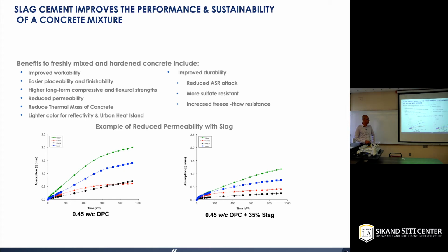It can also react with the alkali in your cement and reduce the ASR attack. And with more reaction taking place in your concrete mix, it densifies the concrete, helping with sulfate resistance and also increasing the freeze and thaw resistance.